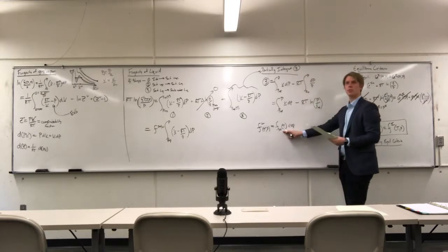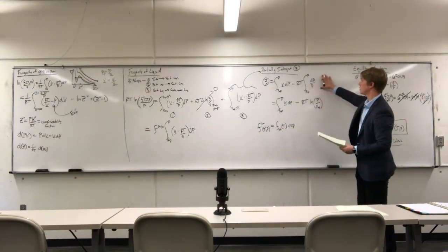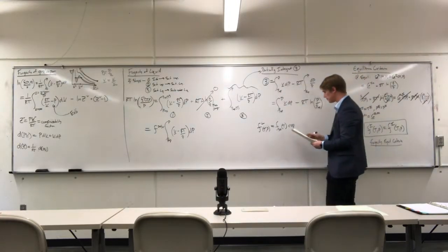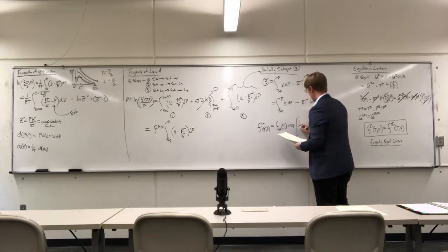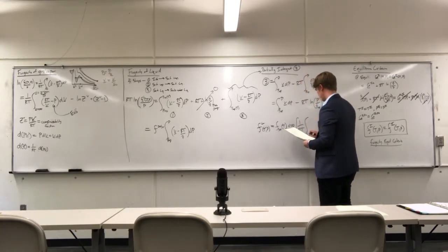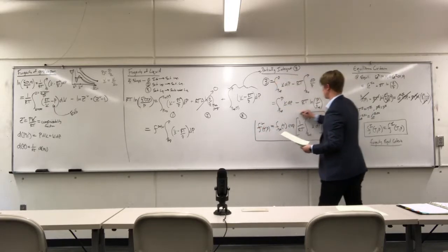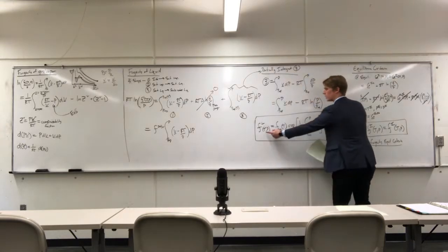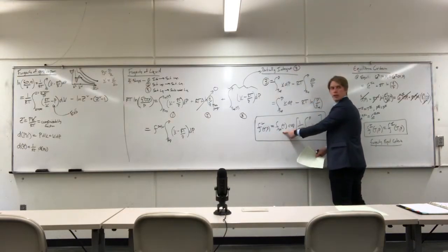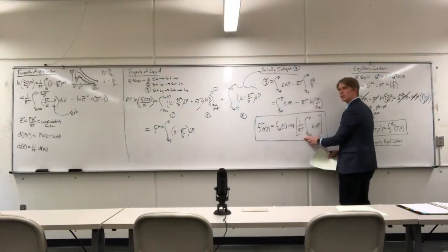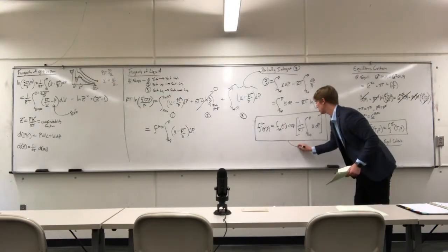because we could potentially continue to pressurize it beyond the saturation point. That's what this last expression is here, right? We're going from the saturation point to some arbitrary system pressure. But then we have an additional term here. This is our fugacity of a liquid. So the fugacity of a liquid is equal to the fugacity of the saturated fluid. This is the same thing as the fugacity of the saturated vapor as well. And then we have this additional term right here, which is what we call the Poynting correction.